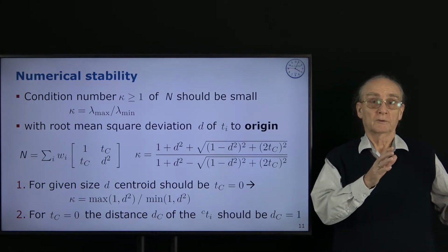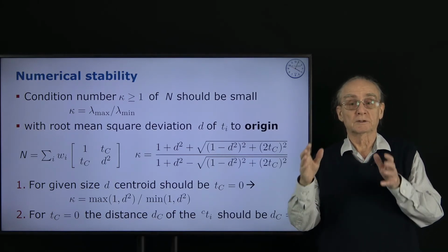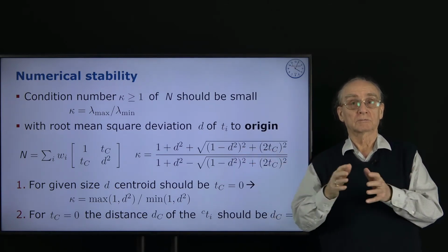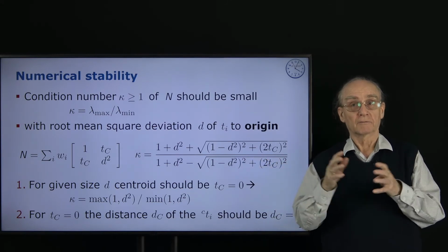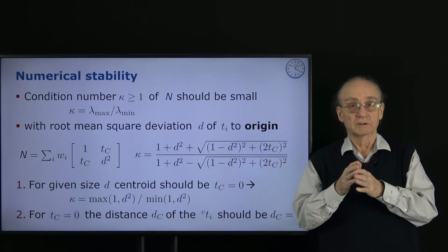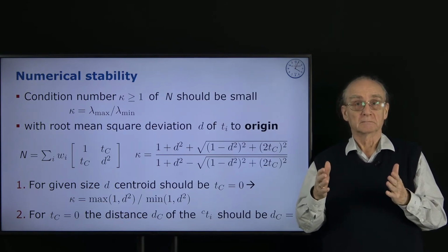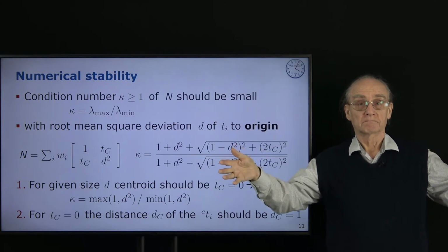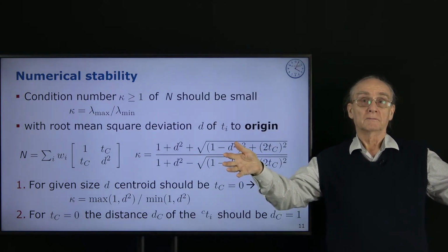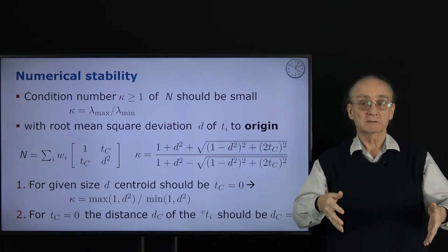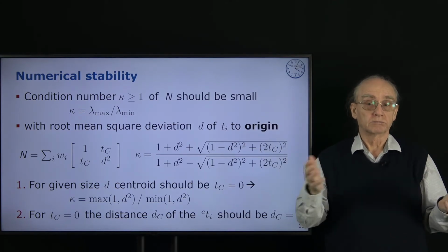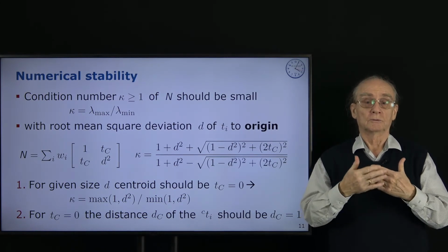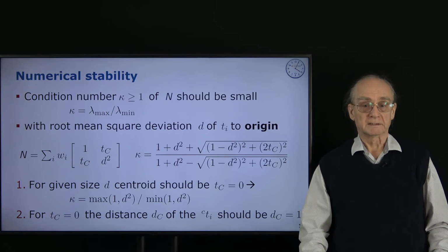For the centroid, we shifted the coordinate system into the centroid, and now we scale the given coordinates such that the average squared distance to the centroid is 1, unitless. So if you have a range of, let's say, plus minus 10 meters, you divide all coordinates by 10 meters and get values around plus minus 1. So you work with unitless entities.